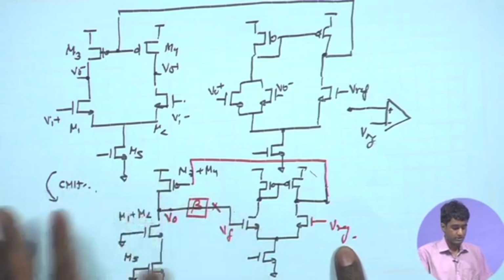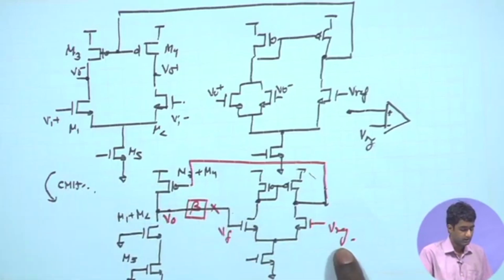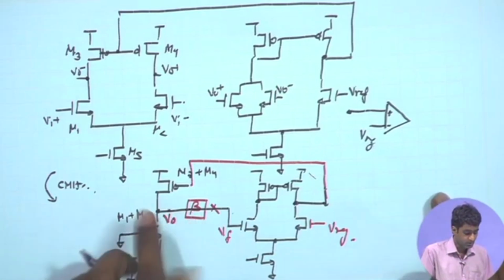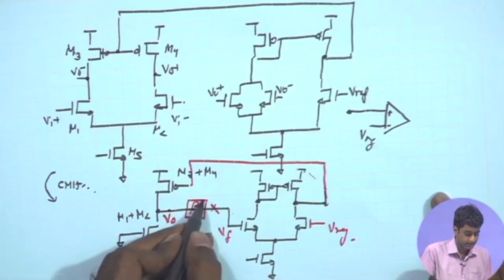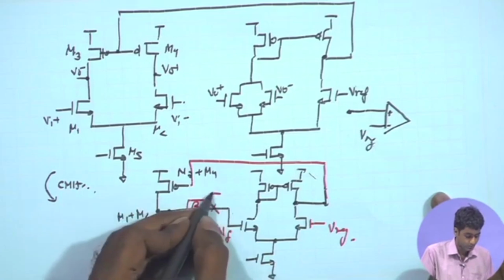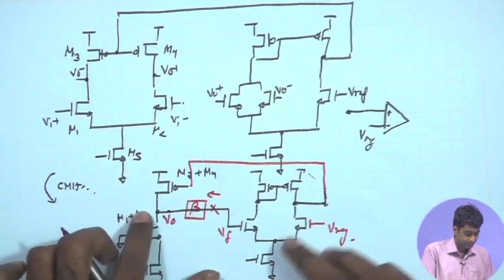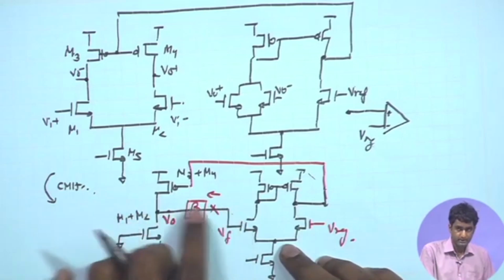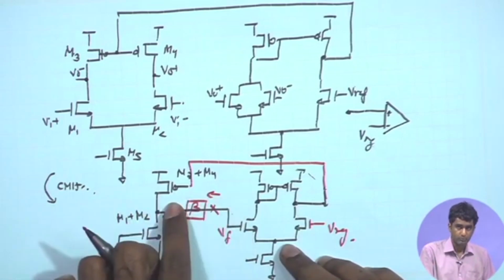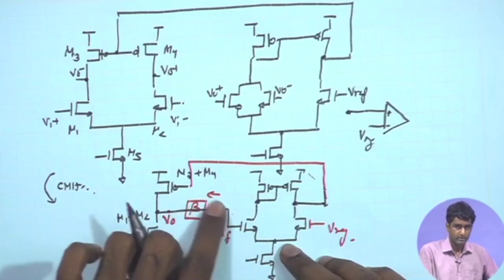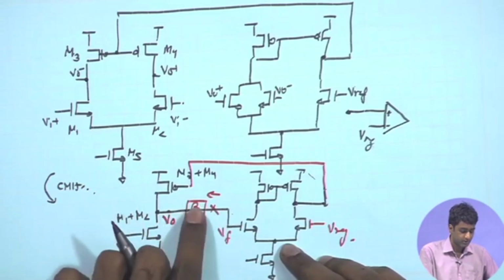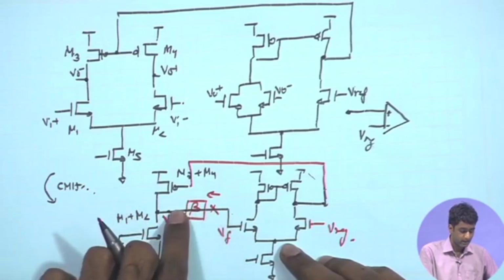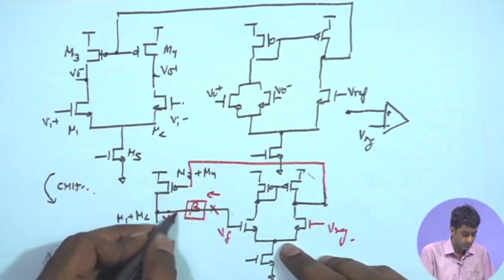Therefore, you have a shunt connection at the output, and so we have a series shunt configuration. While opening the loop for a series shunt configuration, for the beta network over here, looking at the output port of the feedback network, the configuration is shunt, and therefore, we will be applying a ground terminal over here.